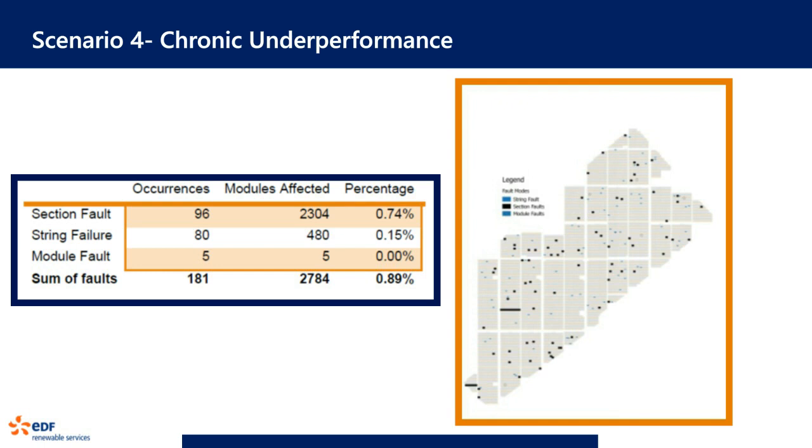So, in here we had string faults, which, in a series problem, what we're really seeing is that a string fault really represents a module failure or a wiring failure in that string. And again, at low current, it's hard to get with handheld tools or to see with your traditional diagnostics. There were some individual module faults, though frankly not as many, that were really like section faults within the module, which may have been problems that were virtually impossible to find with your normal tools in the field.